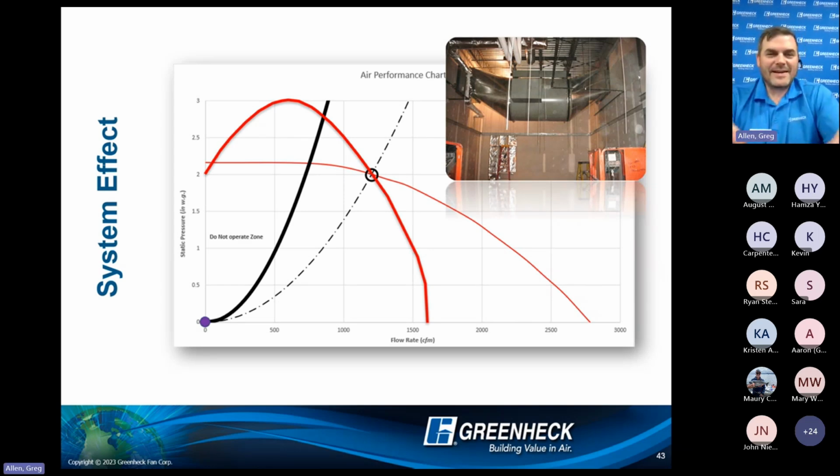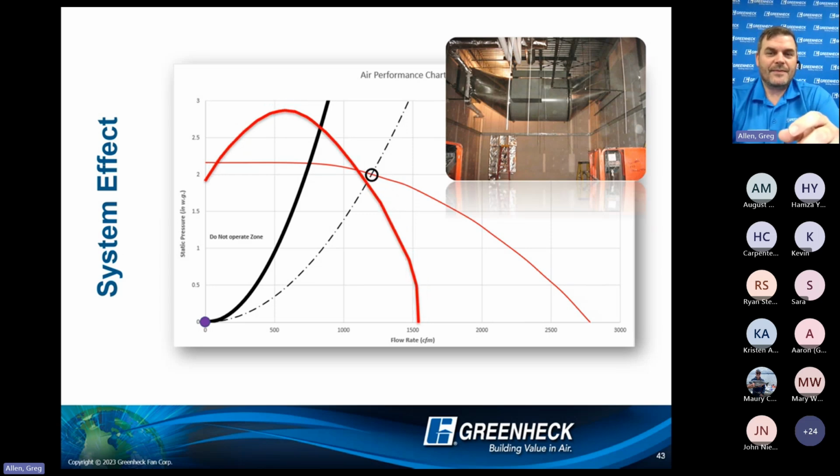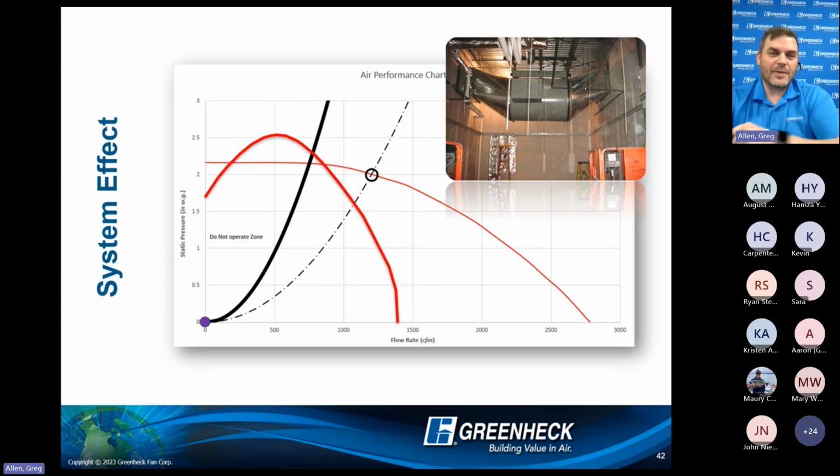So I wanted to get to this point where I showed you that the best selection of a fan can be affected by final installation. I don't think that surprises anybody. But the surprise here comes at how much it can affect that fan's capability to move air. And I wanted to throw it all back onto a fan curve, which is where we started.